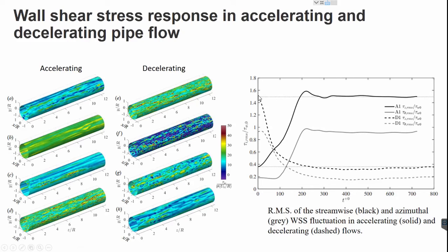An interesting thing to see here is that if we see the streamwise fluctuation, it decays and it undershoots the final steady state, which is this dashed line. This dashed line is indicating the final steady state. It undershoots, which shows us that the flow tends to relaminarize, and then it becomes turbulent again. So yeah, there are some interesting characteristics here.